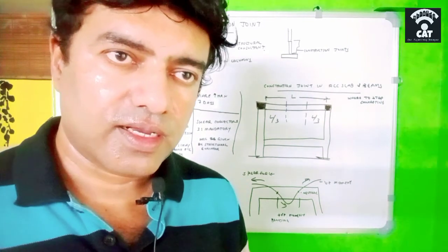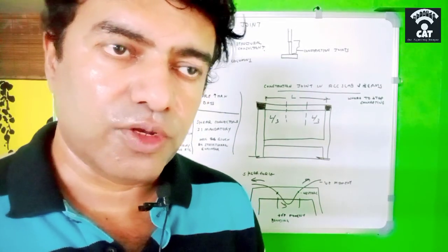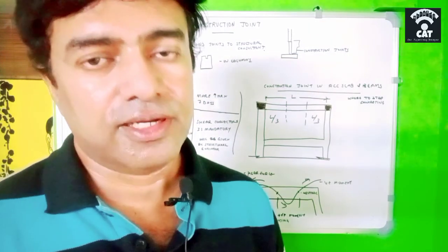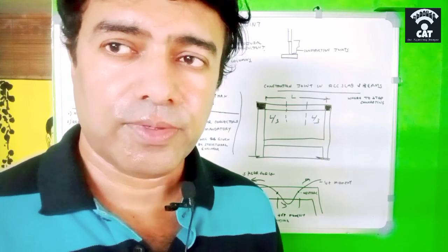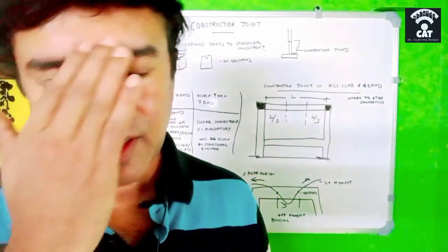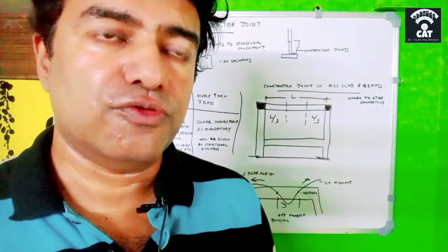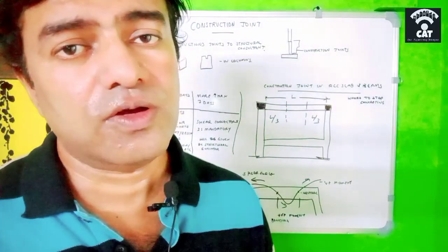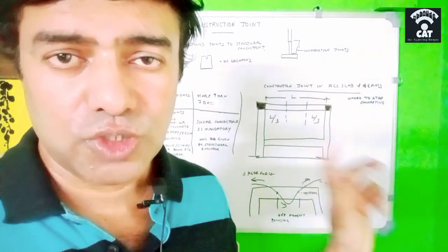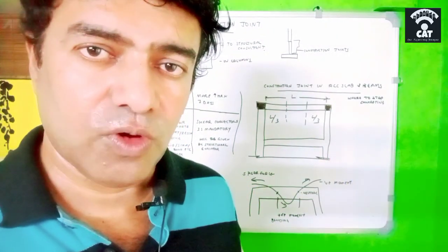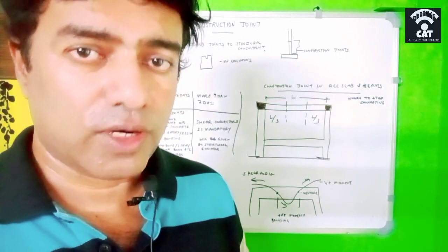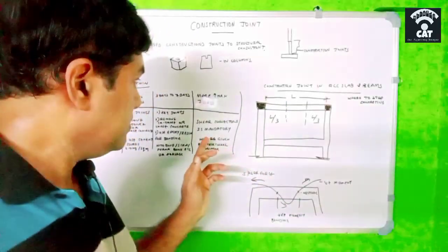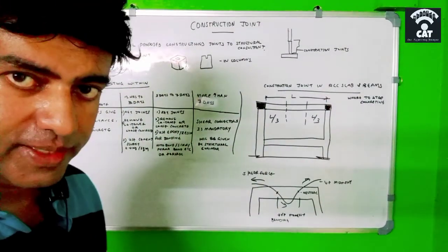And if the construction joint happens to be not within this time interval, and it may be between 3 days and 7 days, because of some reason we cannot do the work within 3 days, then also we go for the same key joint, removal of laitance or loose concrete. But here we apply epoxy or resin for bonding.